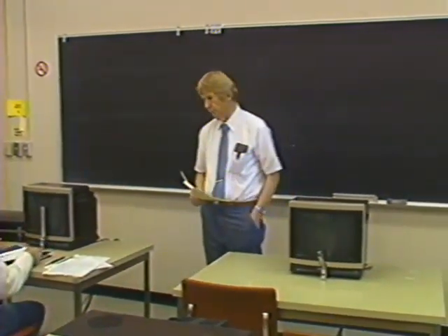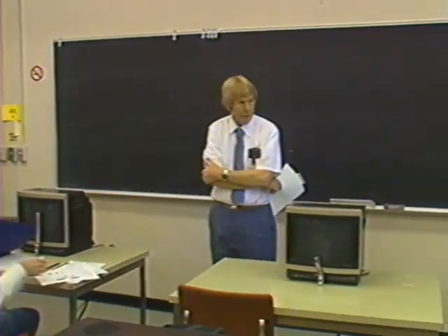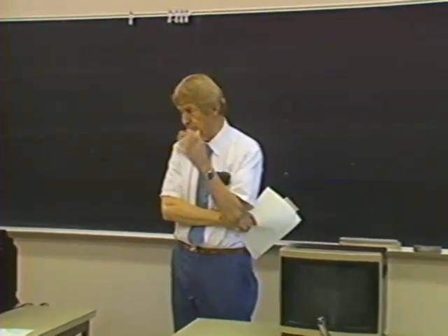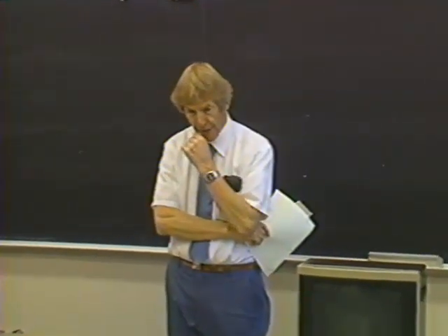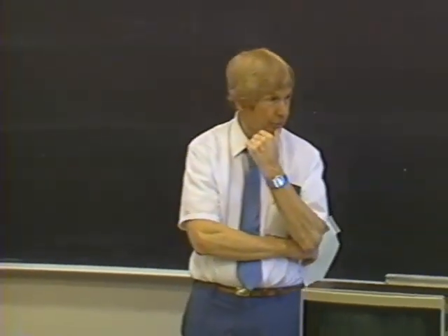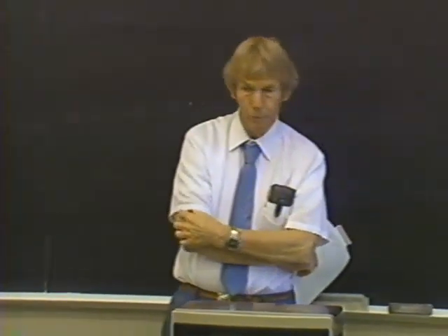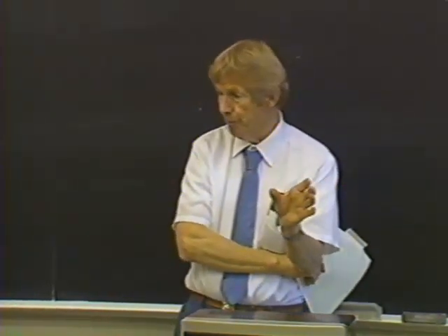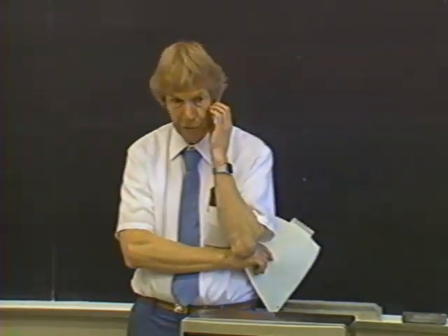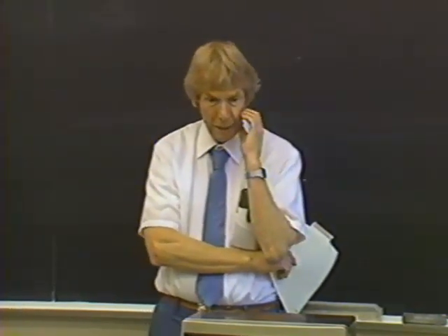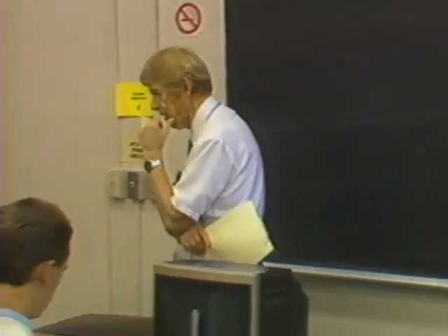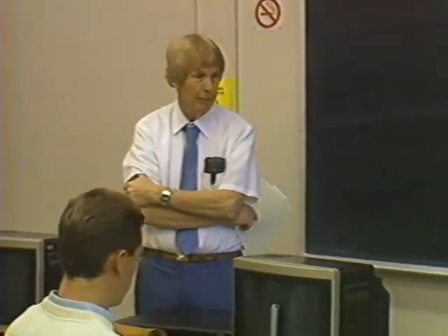Rayleigh distribution and methods of calculating the significant height of waves from wave spectra, or from wave records. We talked about one generation of waves and discussed the fetch limiting and duration limiting aspects of wave generation. And then we began talking about the initiation of movement of sand by waves.